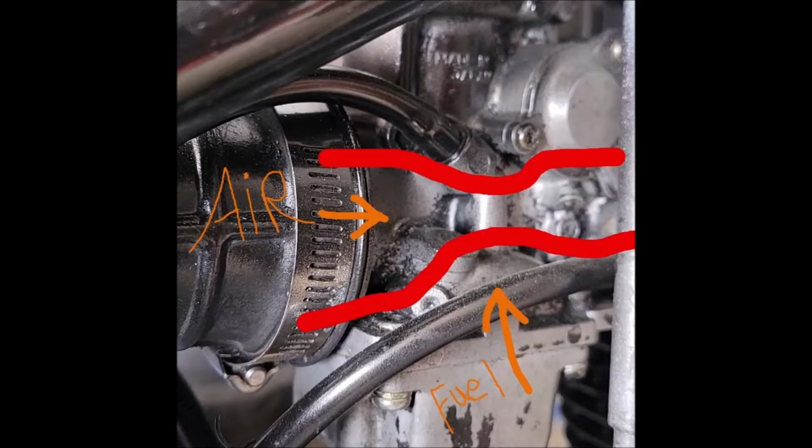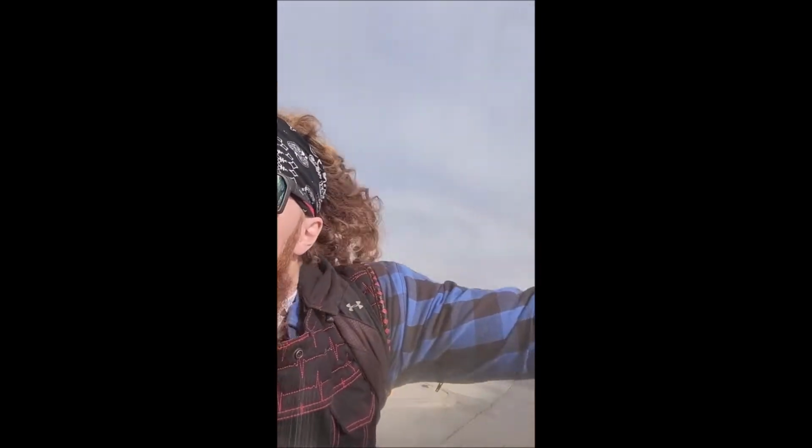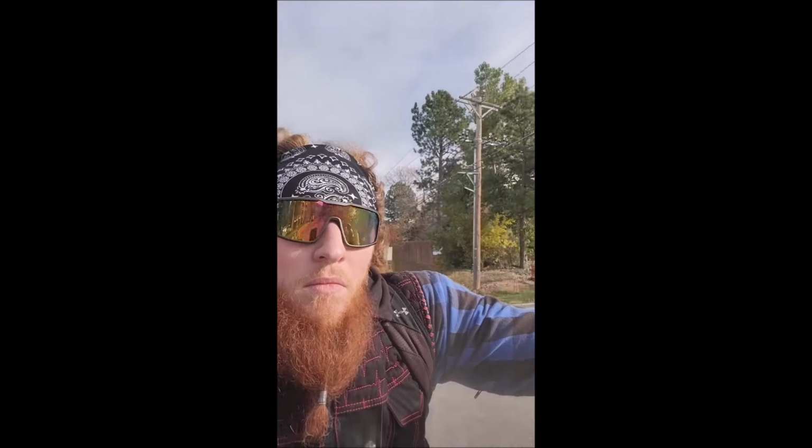Before the air and the fuel arrive at this point, they are controlled by a device called a jet. A jet simply provides more or less fuel or air depending upon the vacuum created in the carb at that particular time. Bigger jets will give you more, smaller jets will give you less. Each jet will be activated depending upon the needs of the engine at that particular time. However, because this is a mechanical process, the carb does not adjust instantaneously. This can leave you in a rich or lean state if you make sudden changes to throttle position.